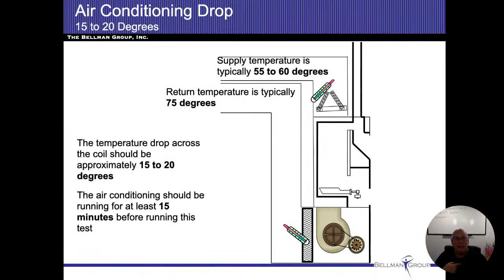I normally don't take temperature readings on the filter side of the fan. I kind of just look at the thermostat when I lower the thermostat to see what the temperature is, because that's the same temperature of the air that's going to be coming through it. But I do take the temperature above the plenum up there, and I'll usually either remove the humidifier and get access to that area. I'll look for gaps in the ductwork itself that comes in there, and if I can't, I'll find the closest radiator.